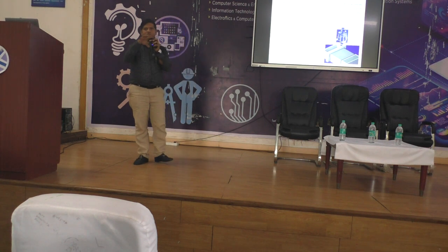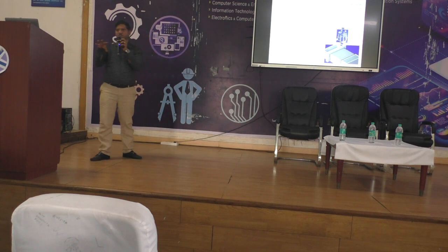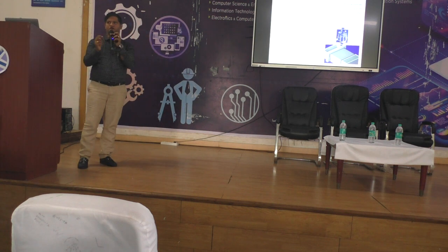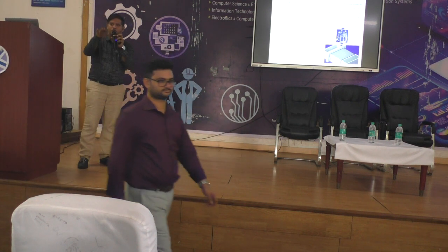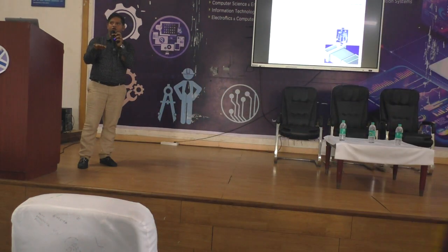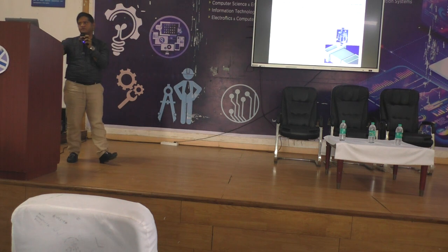Once the selective region of the powder has been melted, the bed goes down a distance equal to the thickness of the slice, and then a new layer spreads. Again the laser selectively melts the newly spread powder as per the slice information, and this continues layer upon layer to make the 3D component.